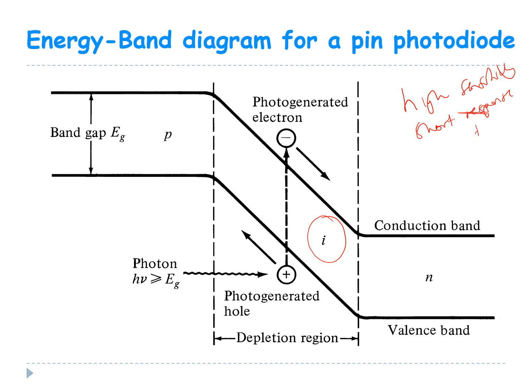The shorter the response time, the better the photodetector, because you quickly want to detect the presence of light. A very important way to do that is to make sure that all the generation is done within the depletion region, because in the depletion region, carriers move due to drift.